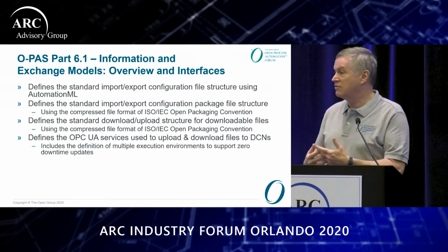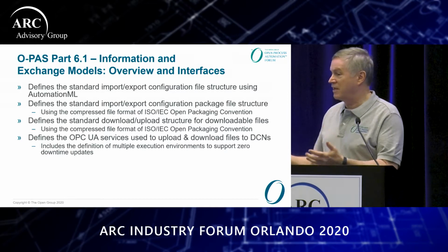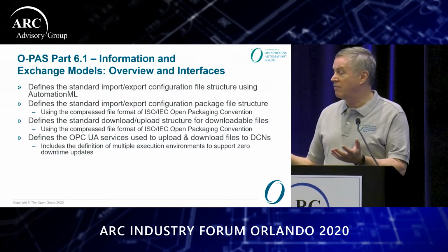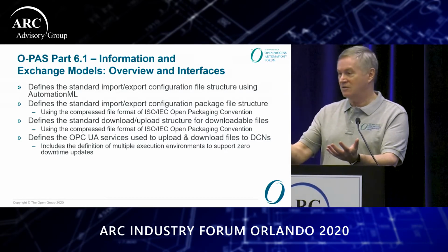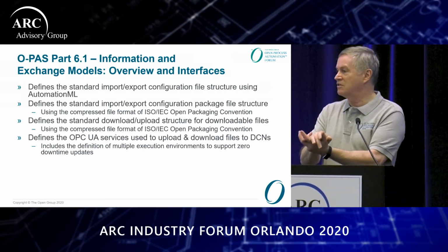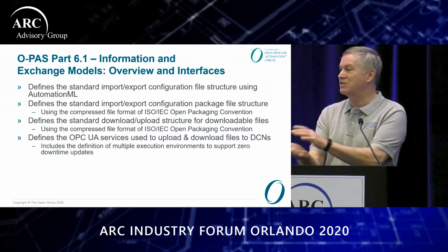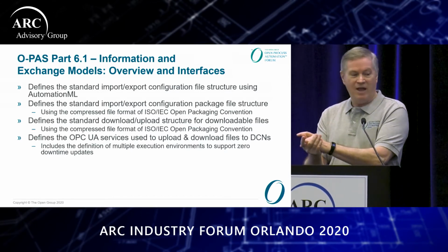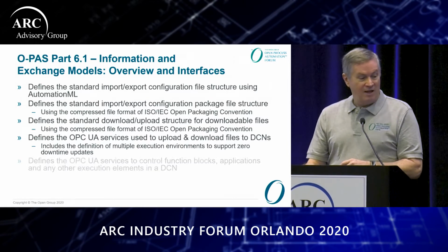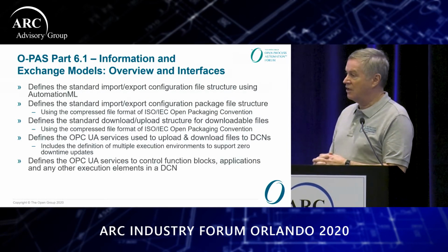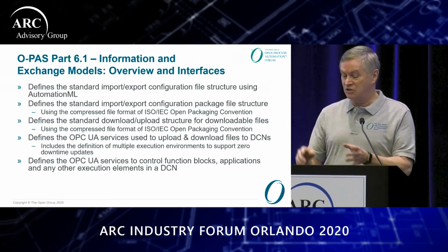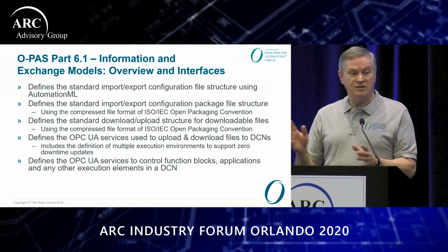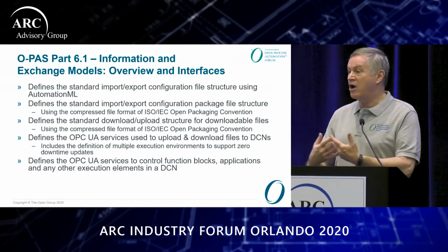So using a lot of the models that existed in some companies like Dow and others, we basically say we have multiple environments. I can be running one environment and downloading to the other environment. I can turn it on to simulate or watch to make sure that there are no changes, and then provide a mechanism to switch over my environment. So I don't have to shut down my system when I want to do updates to my applications and my configurations. And then finally, we have services, again OPC UA services, to actually control the applications and the function blocks, to turn them on, to turn them off, to pause them and control them in a common manner.